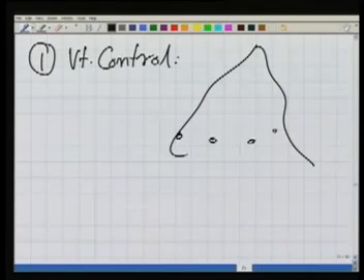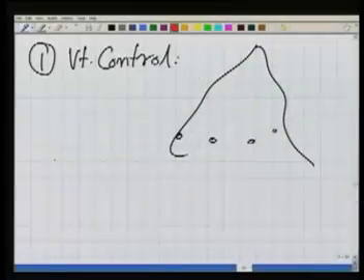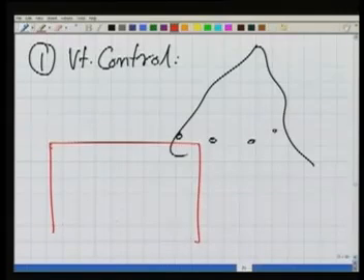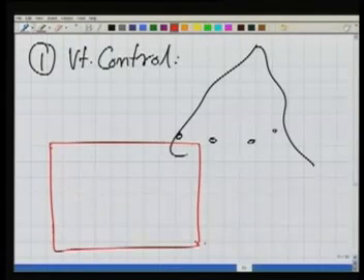Still my contouring is not complete, because right now I know there in the ground that these points have same elevation. What I need to do, because ultimately a contour is, we want to plot it on a map. We want to show these points here on the map and join them by a line.